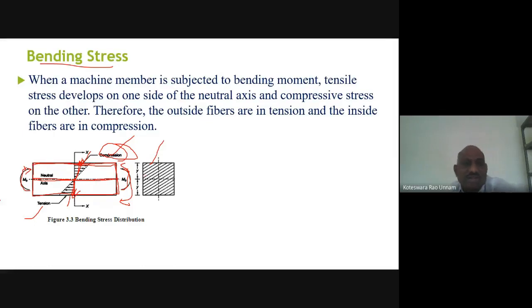You can say the neutral axis is nothing but an axis drawn through the centroids of all those neutral layers. We call it the neutral axis. Now above or below the neutral axis, the signs of the stress are opposite. Of course, these are normal stresses only, but here the signs are different. One is in the positive direction, the other in the negative direction. That means one tends to elongate and the other tends to compress the component. Therefore, in case of bending stress, even though you have two types of stresses, tensile and compressive, induced, for the design criteria we will take the maximum value only.